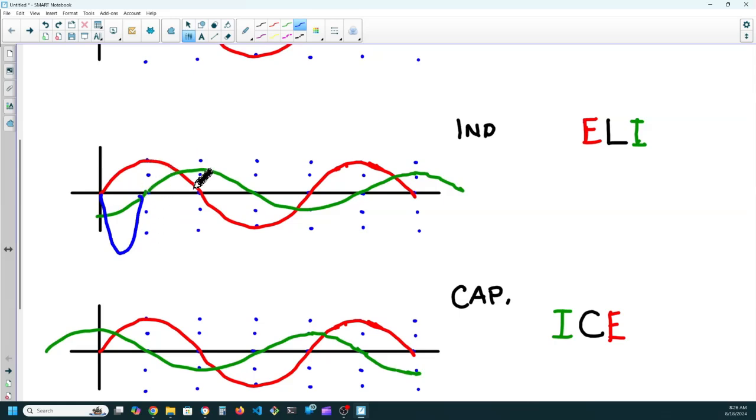And in the next 90 degrees, we have a positive voltage and a positive current. When we multiply them, we get a positive power. And when we have a negative voltage and a positive current, we have a negative power. And negative current, negative voltage, we have positive power.